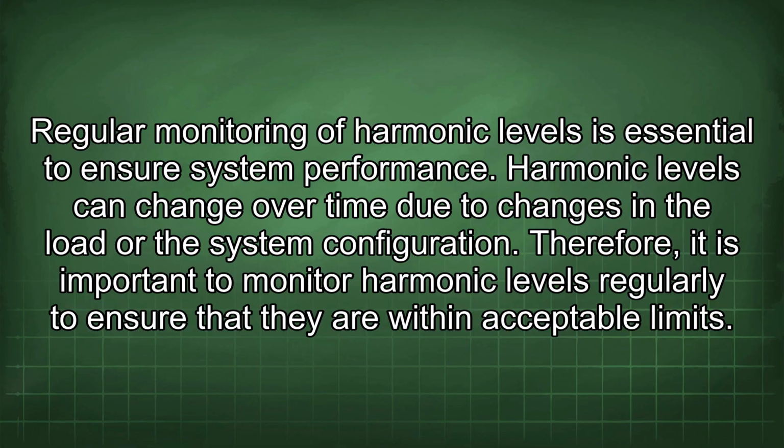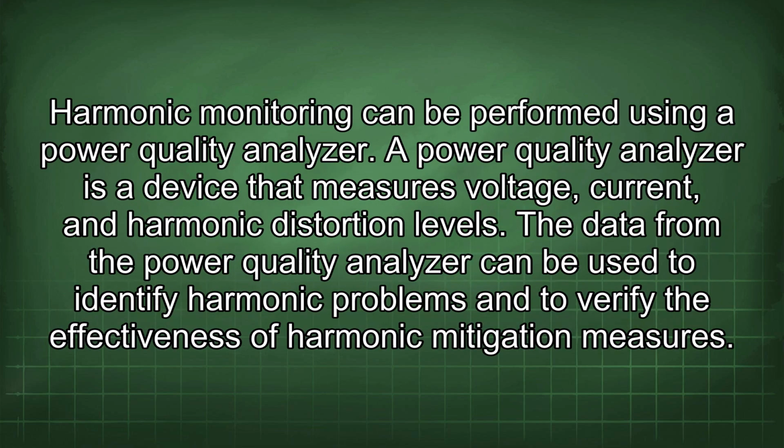Harmonic levels can change over time due to changes in the load or the system configuration. Therefore, it is important to monitor harmonic levels regularly to ensure that they are within acceptable limits. Harmonic monitoring can be performed using a power quality analyzer. A power quality analyzer is a device that measures voltage, current, and harmonic distortion levels.